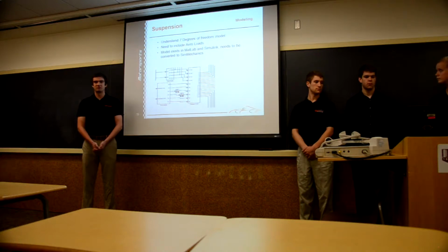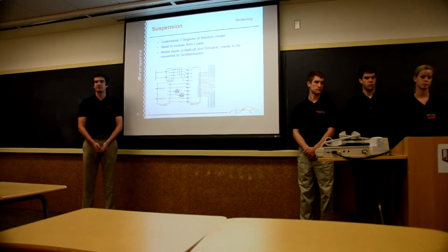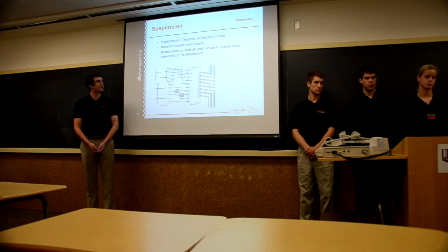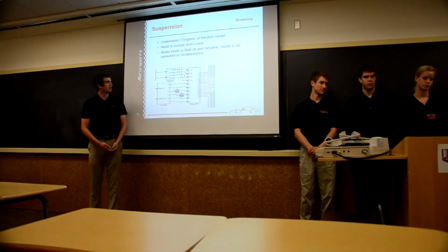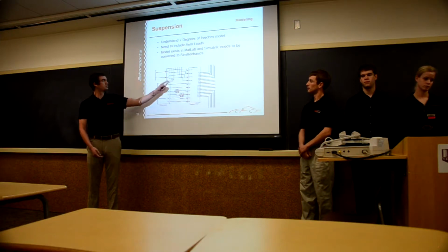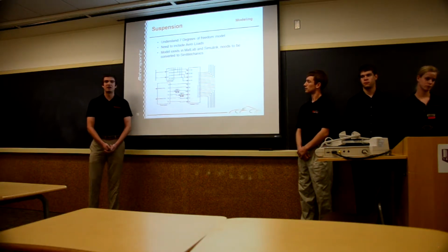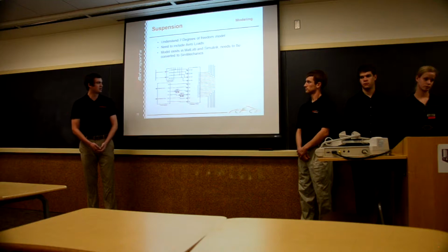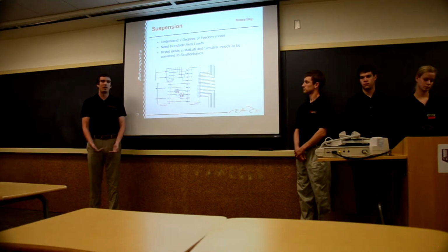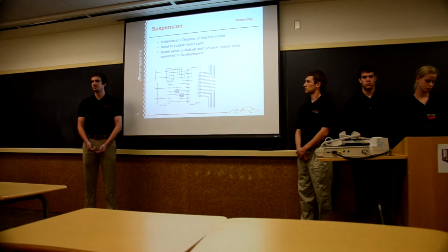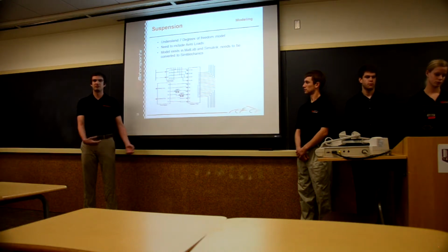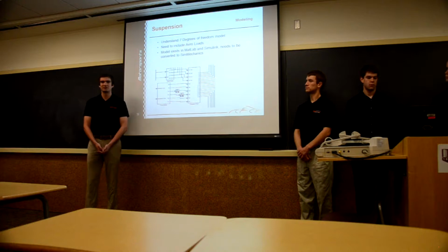Then another thing to adjust is the 7 degrees of freedom model, which was developed by an FSAE alum, Chris Farabee. Currently it's modeled in Simulink, but most of it is all road inputs in this block, and it doesn't account for any of the new aerodynamic loads that'll be coming. While adding the aerodynamic loads, I'd like to change this from Simulink and MATLAB to SimMechanics, which is a lot more user-friendly because it's all based on springs and dampers and not doing the state space or transfer functions correctly.